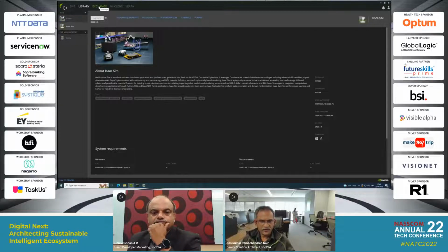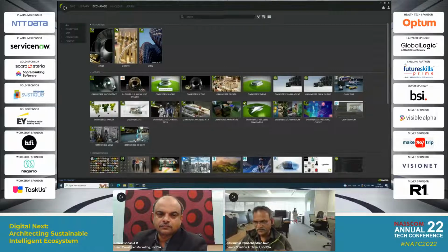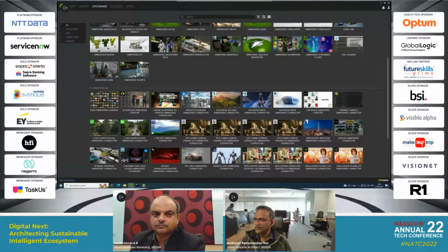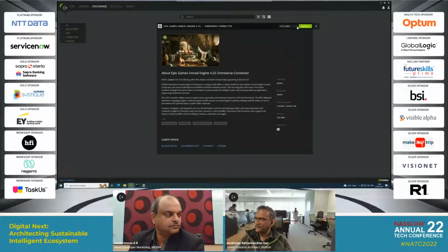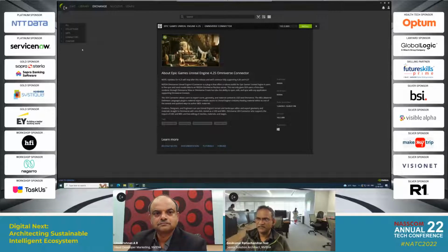If I want to install something more, I can go to Exchange. Exchange is the place where all the applications, all the connectors, all the assets, all the content is listed, and it's categorized as well. So if I want to install, let's say, the connector for Unreal Engine, I just click on this and say install. And if I want a specific version, I can go to all builds, choose a specific version and install that as well. It's that simple. Everything that you install gets installed inside Omniverse.